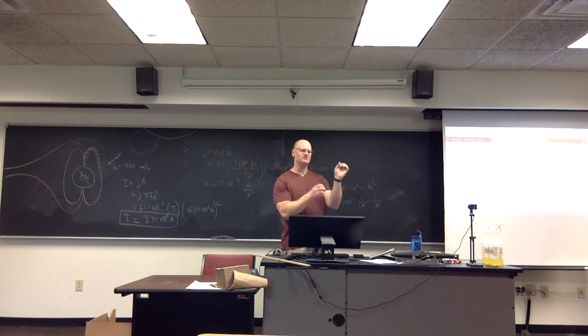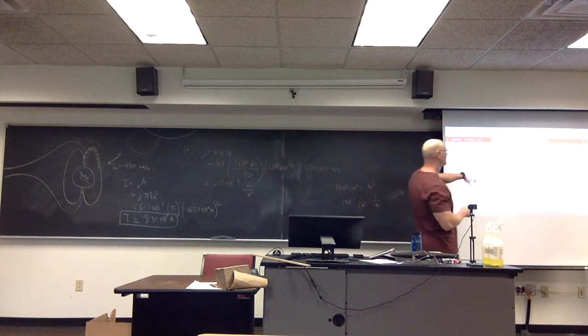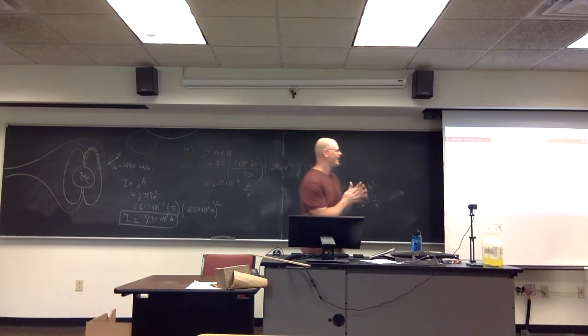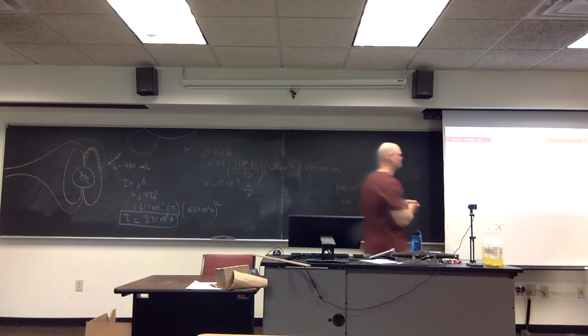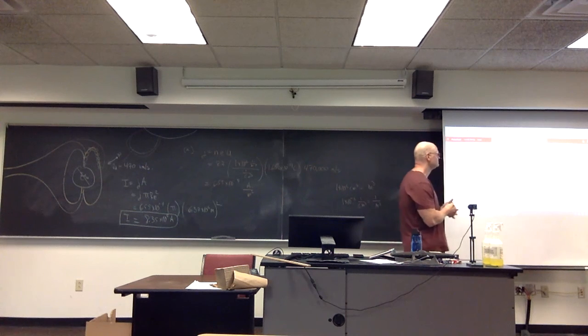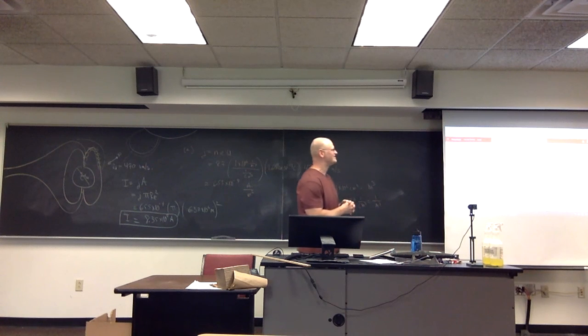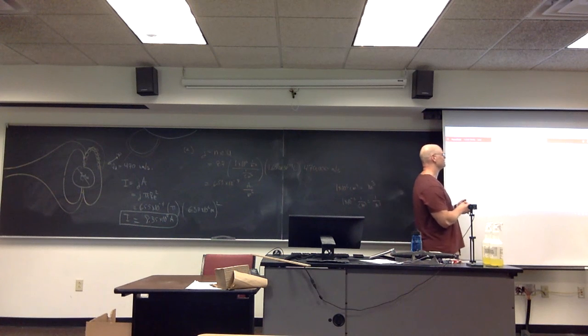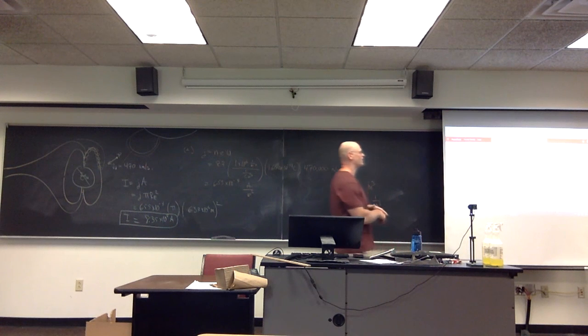The higher the gauge, the smaller the cross-sectional area. The smaller the gauge, the bigger the cross-sectional area. So in this case, all it means is that the gauge is 0.04 inches. So this is the diameter of the wire. From here, I want you to calculate the current, the magnitude of the current density, the drift velocity of the electrons, the magnitude of the electric field inside of the wire, and the rate at which thermal energy will appear in the wire.